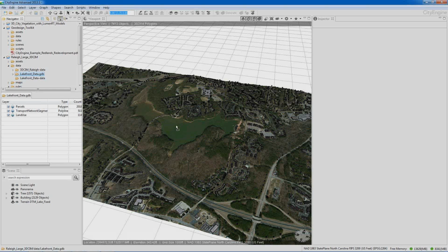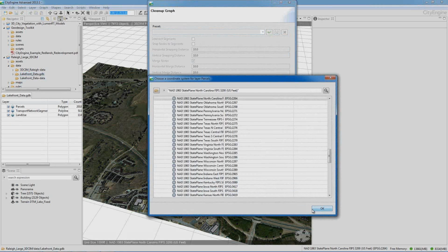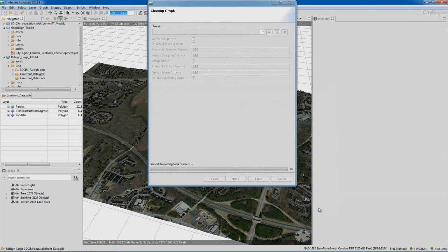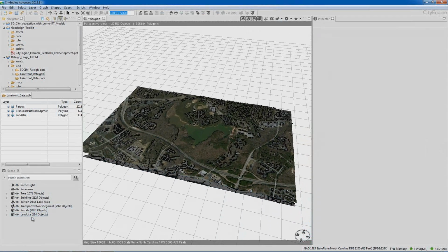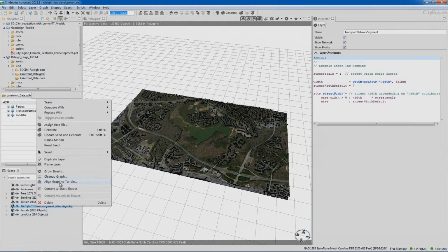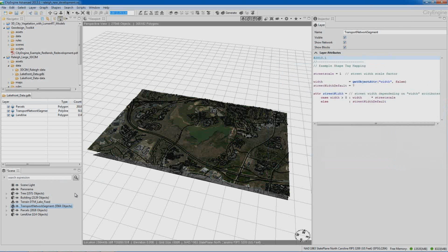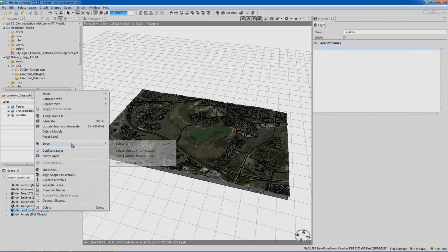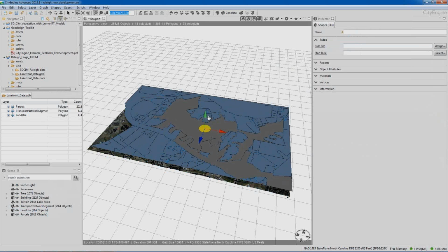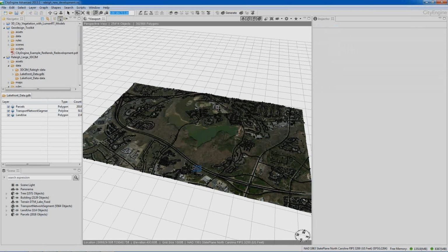So let's go into planning and the urban design process. Once you've built the existing conditions, you can then conduct a model of how the site could look. And let's load in some data. I brought in some streets that I can start to create parcels off of or continue to draw off of. These are from the city street data layers. We also have parcel data that we brought in from the city that we could use if we wanted to. And then land use, which honestly, in my opinion, is one of the most valuable data sets that we can really leverage here to help figure out how this place looks based off of its current ordinances. So I'm going to select the land use layers and just bring them above the terrain for now and hide them. We'll go into this a little bit more in a second on why we're using this data set.